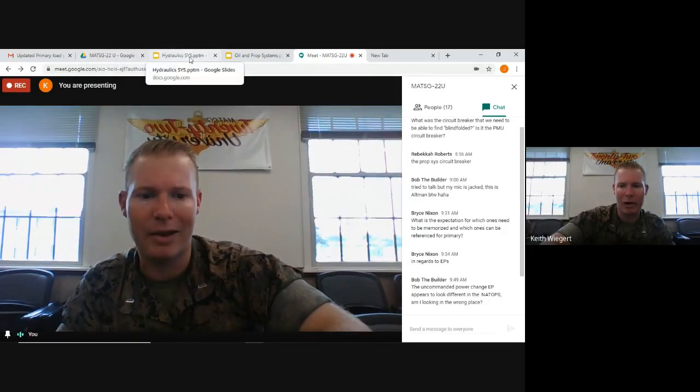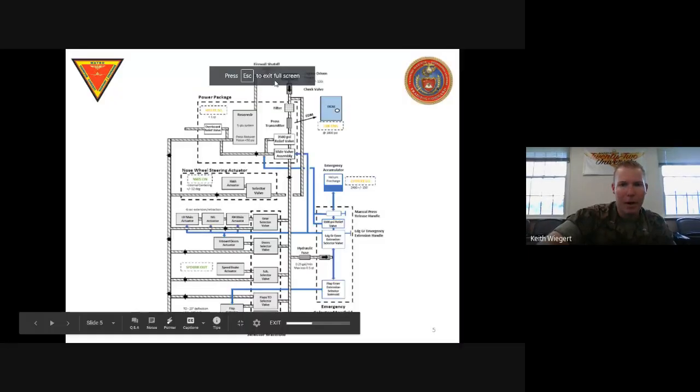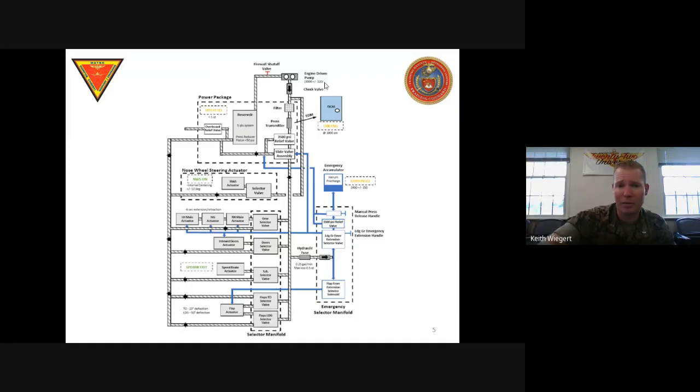So back to the hydraulic system. Coming on back up here. All right. So hydraulic systems, we just got the hydraulic pump, right? That's going to pressurize us up to 3,000 plus or minus 120 psi. Then we're going to go through that one-way check valve because pumps don't like reverse flow. Next, we're going to go through the filter, right? We talked about the filter. Filters filter until they don't, they bypass because dirty fluid's better than no fluid, right?